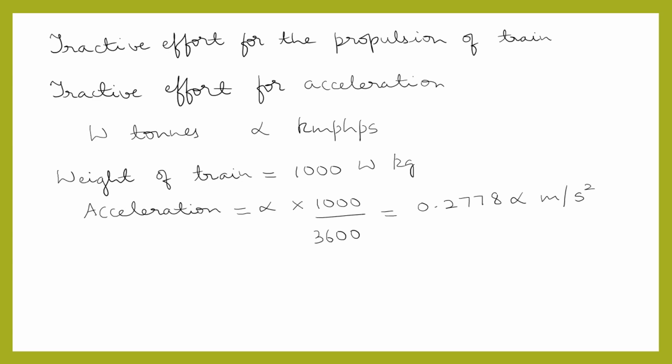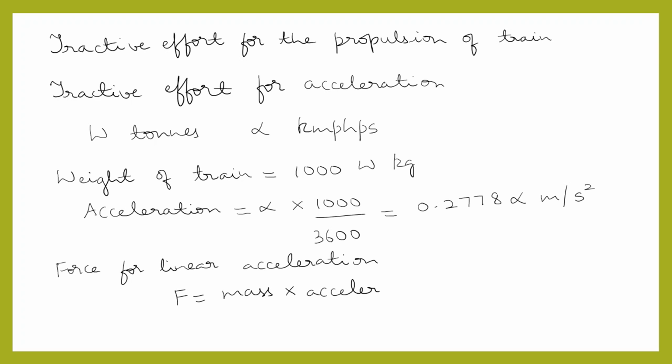Therefore, the force or tractive effort required for linear acceleration is given by F equal to mass into acceleration, that is equal to 1000 W into 0.2778 alpha.